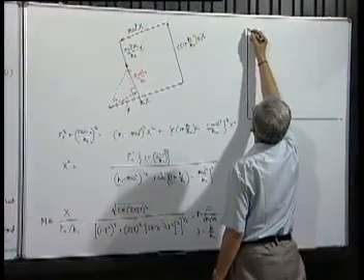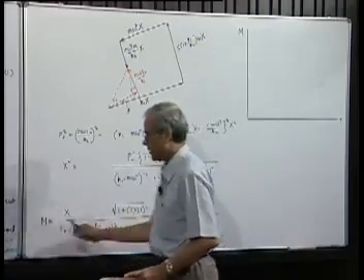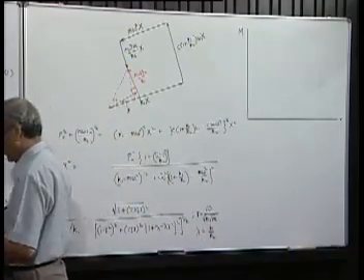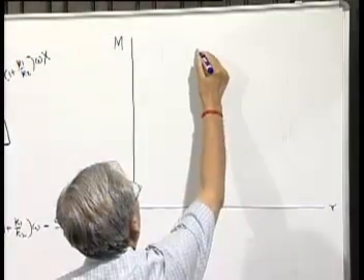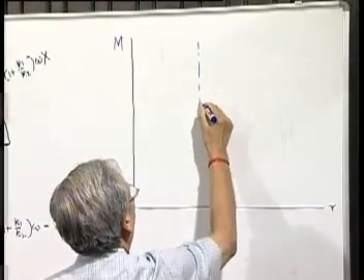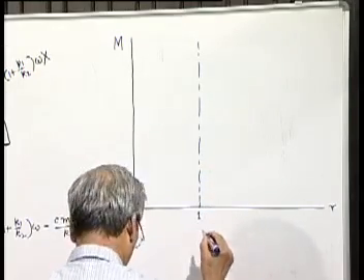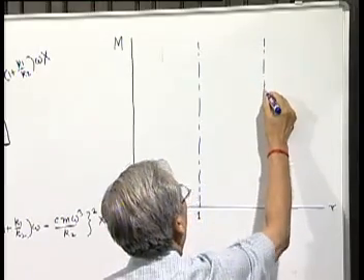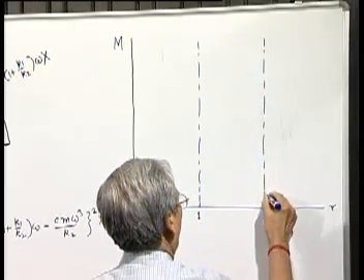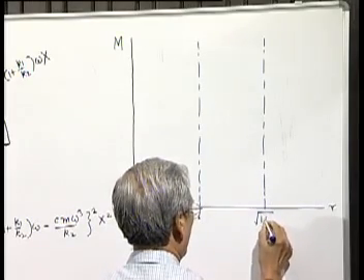The magnification factor is somewhat complicated. Now there are two springs and their stiffness ratios are represented by lambda. The natural frequency of the system is considered to be undamped case, square root of k1 by m, and static deflection obviously also is controlled by the first stiffness, which is the k1. Now here, this one, if we plot,